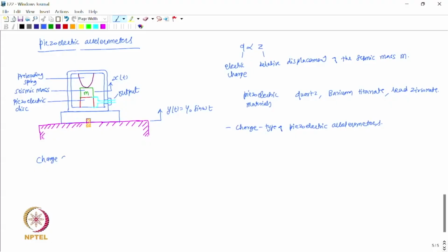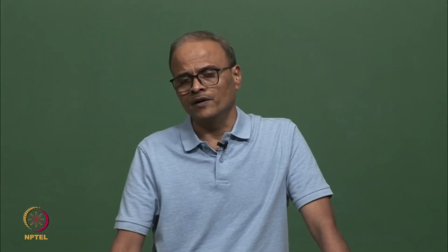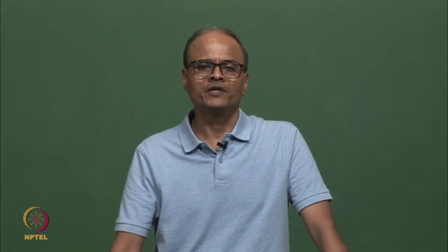The charge output of a piezoelectric accelerometer is a high impedance signal, and therefore, if we directly connect it to any voltage measuring device, then the signal will be severely loaded and the measurement we get will not be accurate.